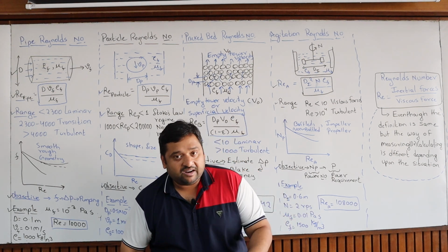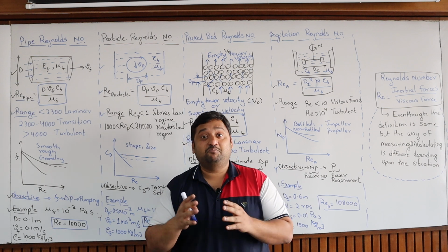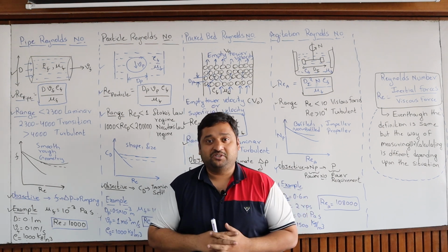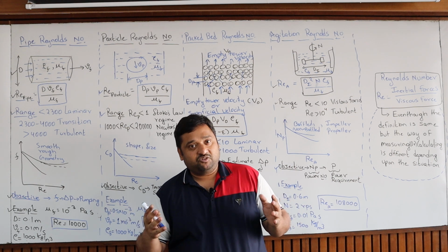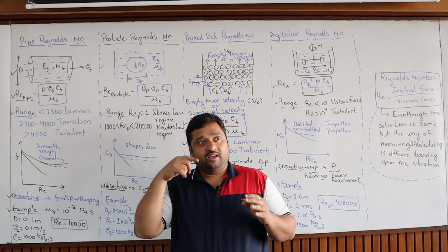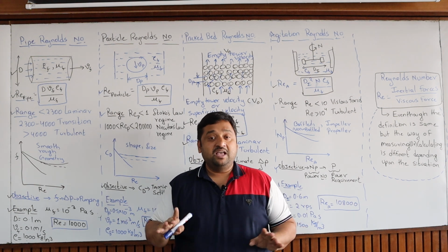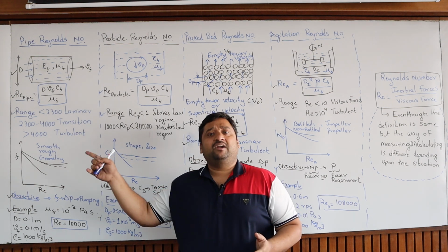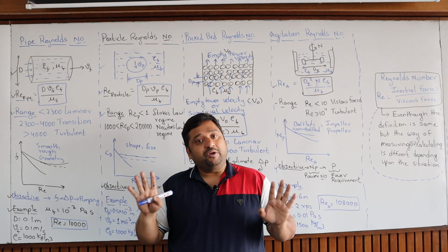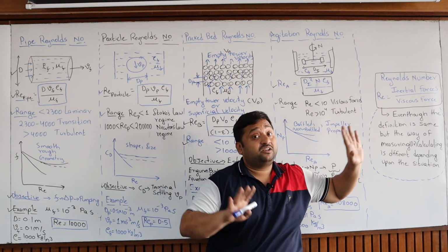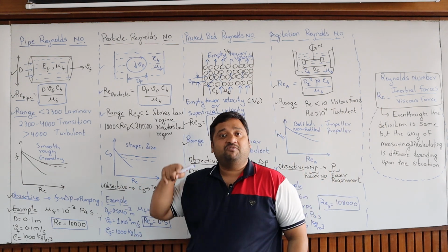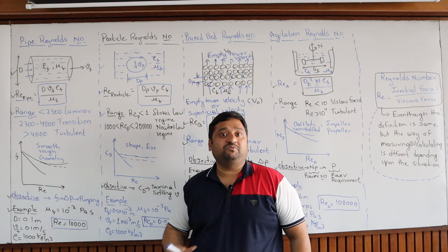I hope you have learned different Reynolds numbers for different kinds of situations, because my students always tend to think that only one Reynolds number exists, but that is not the case. There are different Reynolds numbers for different cases. Everything is doing the same thing, inertial forces by viscous forces, but the way of measuring is different for different situations.